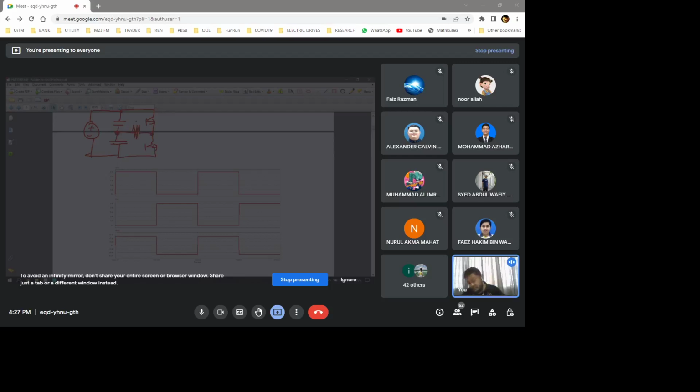First, to understand the circuit, just put in a resistor, then we look at this switch. This is switch 1 and this is switch 2, and these two signals will be fed to switch 1 and switch 2. Whenever switch 1 is on, switch 2 must be off. In practice, there will be some delay here. We don't want both switches turned on at the same time.